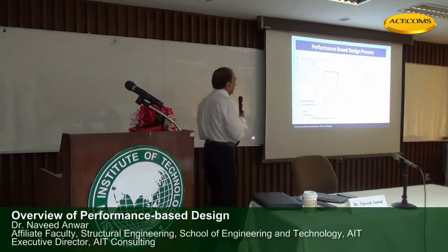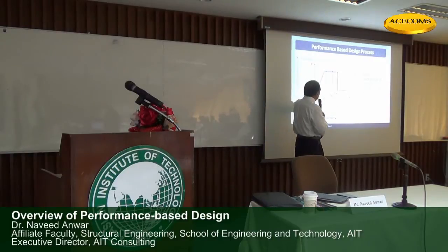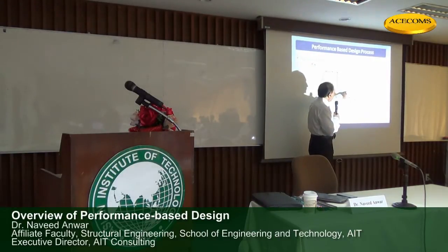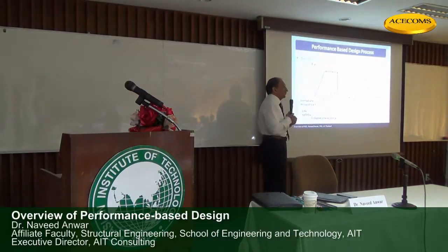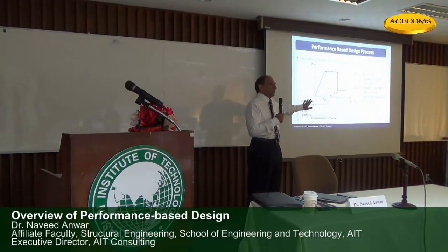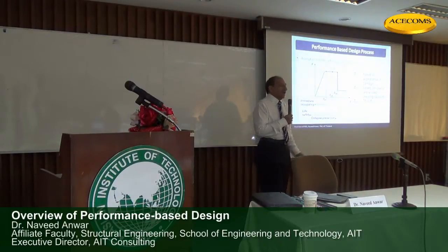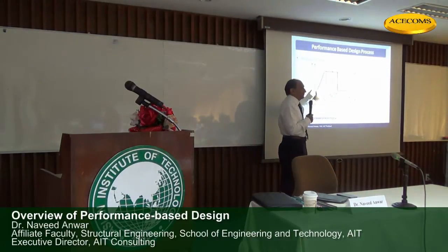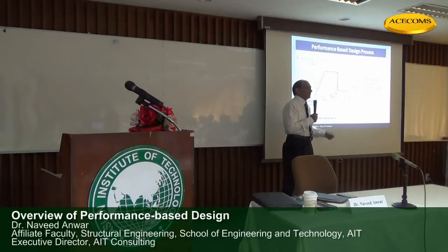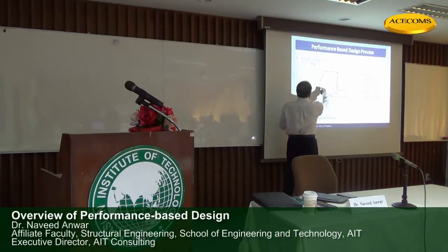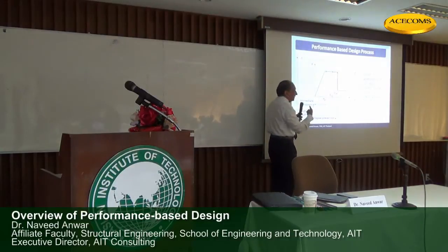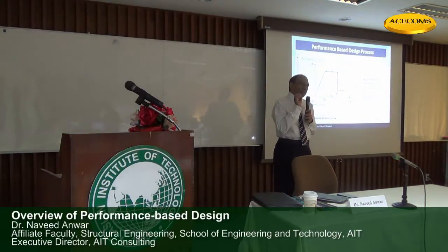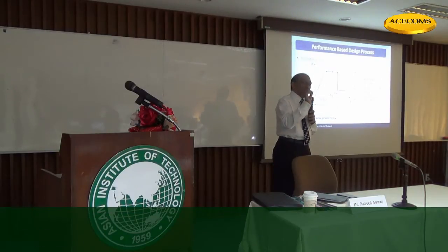So in performance-based design, we can draw the curve between force and deformation. I will talk a lot about this in the second part of the lecture today, which is on nonlinearity. But we can draw this idealized curve, and on that curve we can mark each of the performance acceptance criteria. This is the elastic range. This is the immediate occupancy. So even at immediate occupancy, we are expecting the elastic range may have just been reached. Small cracking may have occurred, not perfectly elastic. It may have just yielded a little bit.